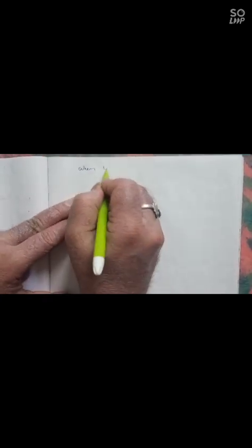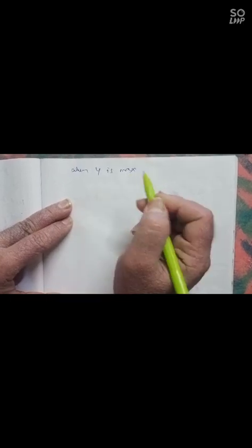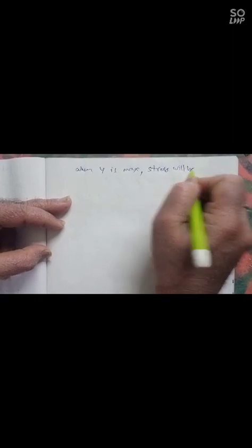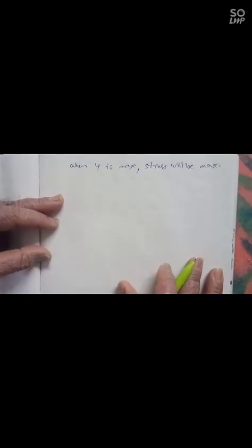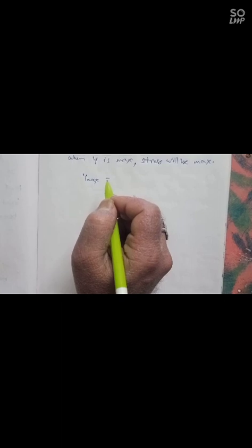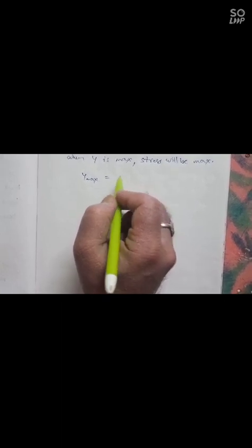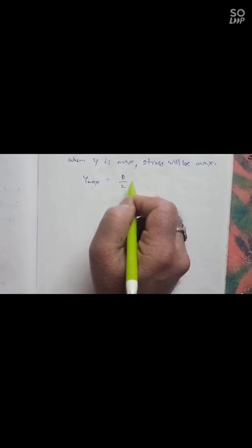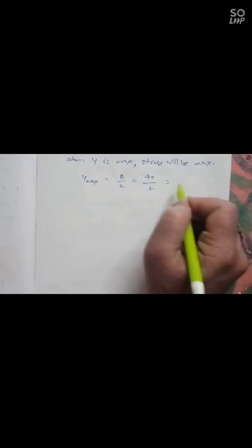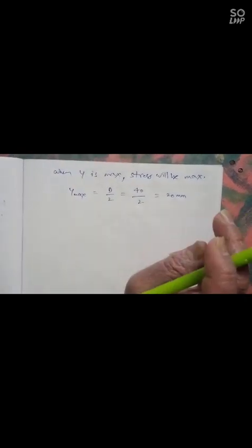When y is maximum, stress will be maximum. Okay, so y maximum, which is available at the top layers. So therefore y maximum is d by 2, that is 40 by 2, 20 mm.